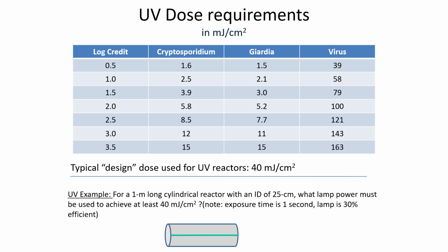I have an old classmate from when I was at Purdue, and he spent most of his career working at a company in New York that makes UV reactors, and they do really sophisticated experiments to find out what the dose is when water flows through it. They're able to put in these little beads that get exposed to the UV, and then collect them and sample how much intensity the beads absorbed as they flowed through the reactor. You can also use computer models to assess the flow trajectory through the reactors.